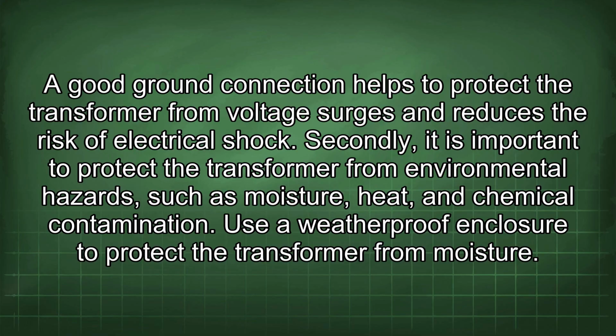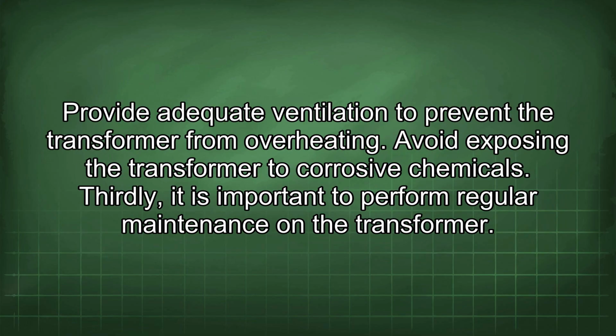Secondly, it is important to protect the transformer from environmental hazards such as moisture, heat, and chemical contamination. Use a weatherproof enclosure to protect the transformer from moisture. Provide adequate ventilation to prevent the transformer from overheating. Avoid exposing the transformer to corrosive chemicals.